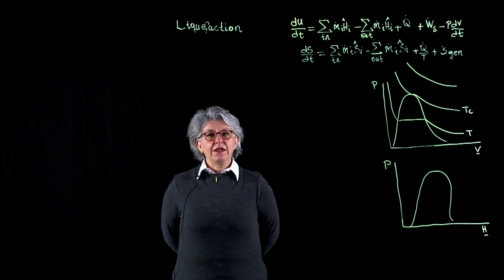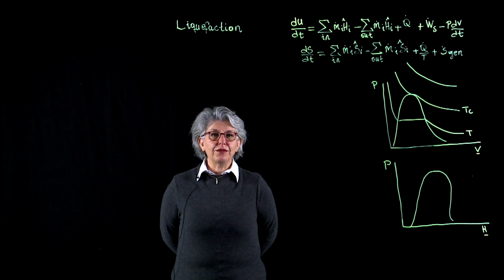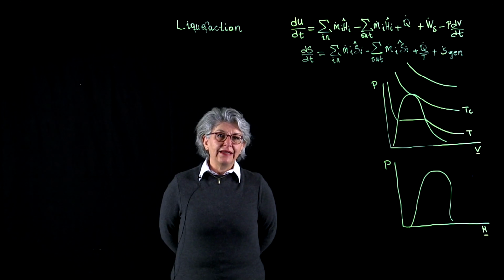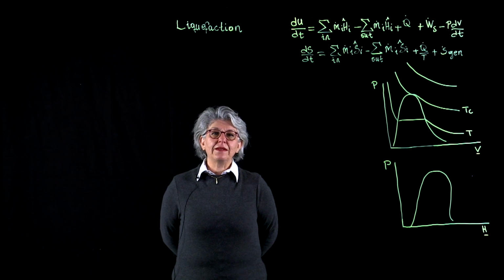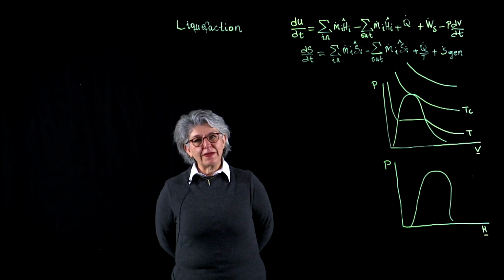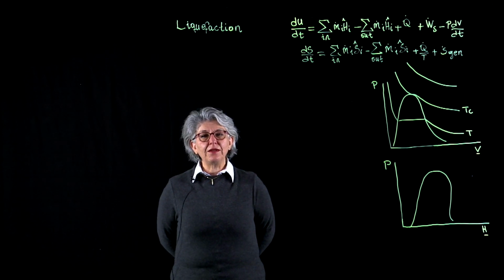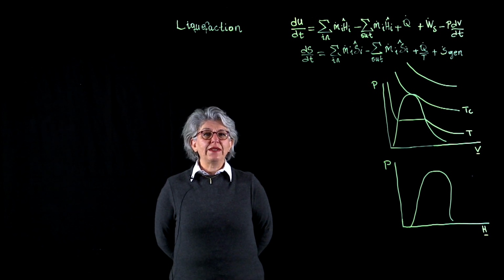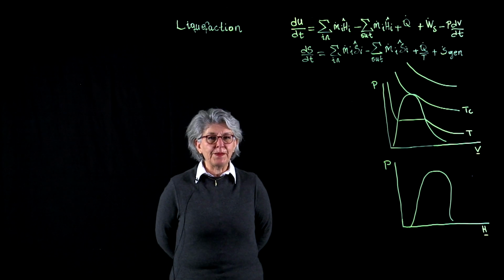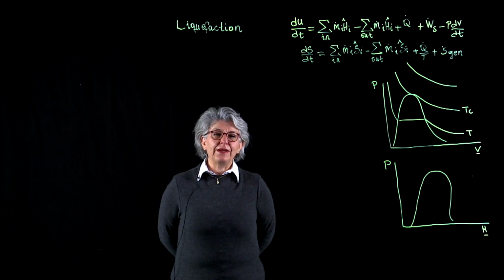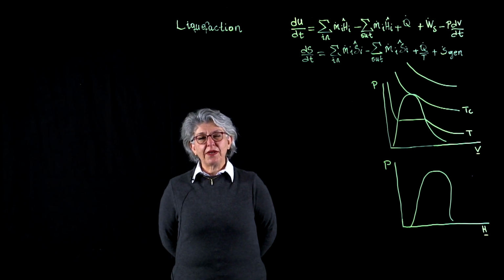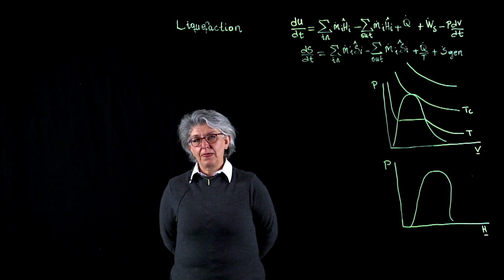Liquefaction is the process we carry out where our gas cannot be condensed either by cooling at constant pressure or compressing at constant temperature. In other words, our fluid is above its critical temperature. So let's start looking at the critical temperature, the subcritical and supercritical temperatures, the isotherms, and how the fluids behave in those domains, and then the necessity for the liquefaction.